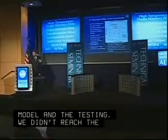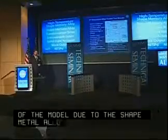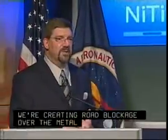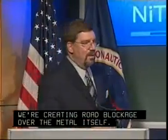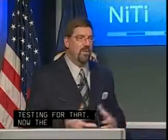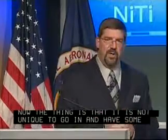We didn't reach the limitations of the model due to the shape memory alloy. What we did was we were creating blockage over the model itself, so we can never break supersonic over the model. So we're going to reconfigure the model itself and go back and do some additional testing for that. Now the thing is that it's not unique to have some kind of a model in a wind tunnel and some kind of a ramp actuating or moving.